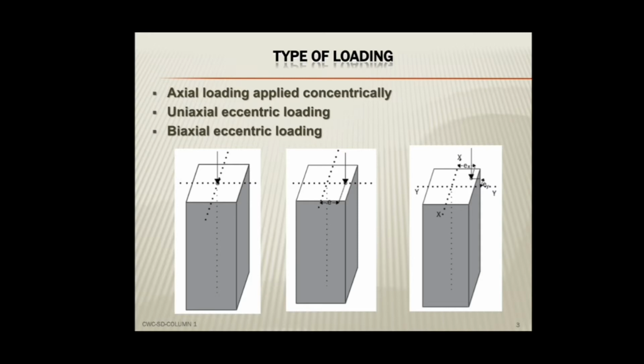For the columns located in the interior of symmetrical simple buildings, the eccentricities under gravity loads are generally of low order and sometimes neglected in the calculations. Such columns fall under the first category. However, the code specifies a sufficiently conservative design to make the column capable of resisting nominal eccentricities.